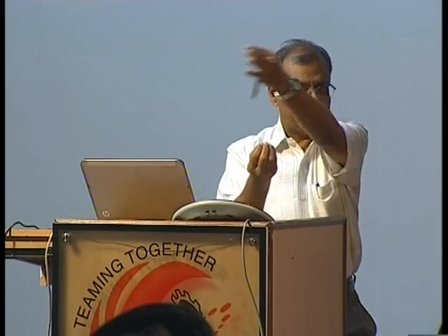But then, after some time, it can find that air, because everything is moving in the cylinder. Let us say some soot was formed because that fuel droplet did not find enough air. But there is air elsewhere. And if you stop the combustion process for some time, this soot will move and get into some region where there is air. But it will not burn because the temperature is not there. So at that time, if you pump some more fuel, that raises the temperature and makes this soot burn. So this is reburning that soot.